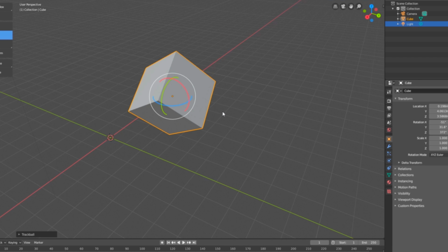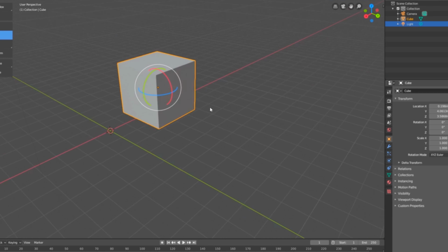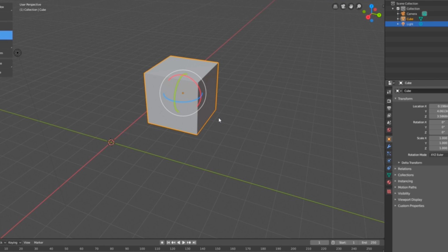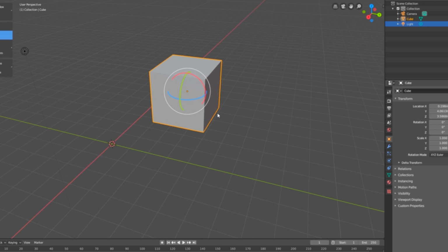Now, before using the Scale tool, I will use the Ctrl-Z shortcut to go back a few steps until the box returns to the starting position. By default, Blender is set up to save up to 32 steps in history. Which means if we use Ctrl-Z, we can go back up to 32 commands.